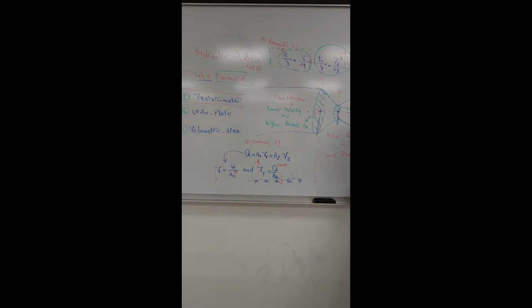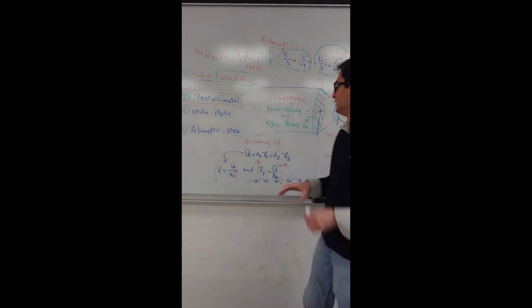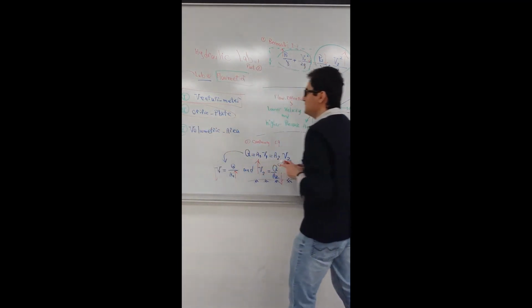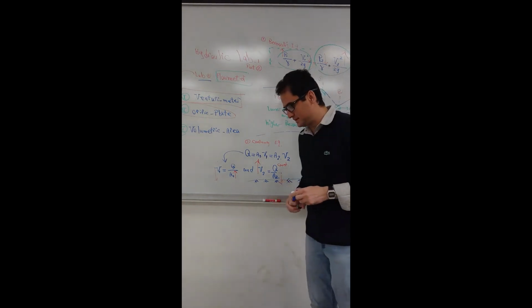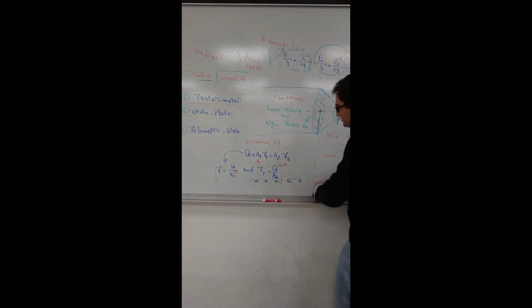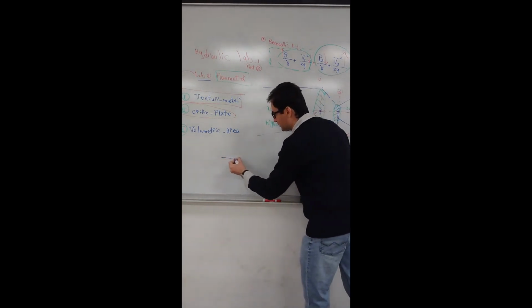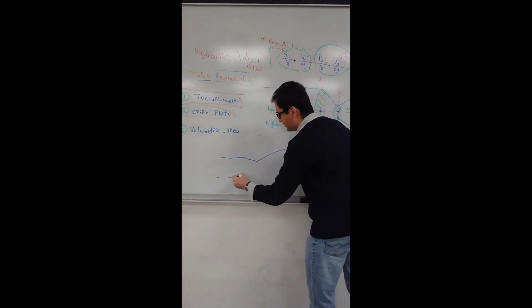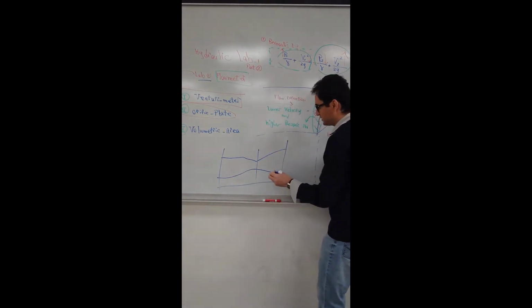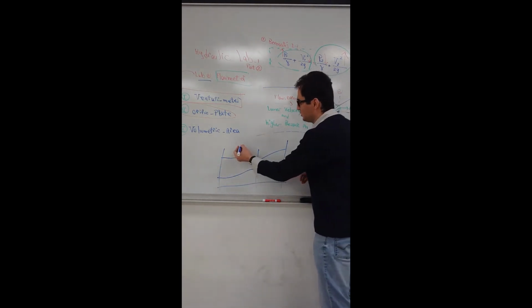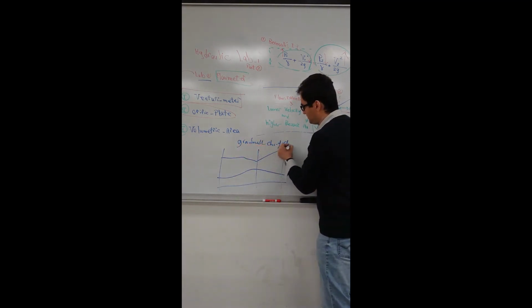The same concepts apply for the orifice plate, the second apparatus. The difference between the venturi meter and orifice plate is that in the venturi meter the change of area occurs in a relatively smooth, longer distance, so it's a gradual change or drop.